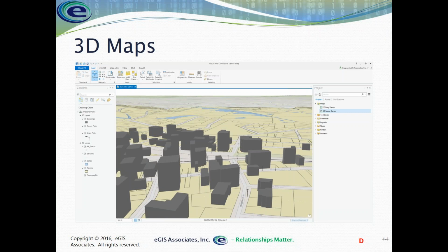A question came in: can ArcGIS for Desktop use a map in 2D after you create a 3D map in ArcGIS Pro? So, okay, ArcGIS Pro uses a whole different set of files than ArcMap. It uses project files, APRXs, instead of MXDs.